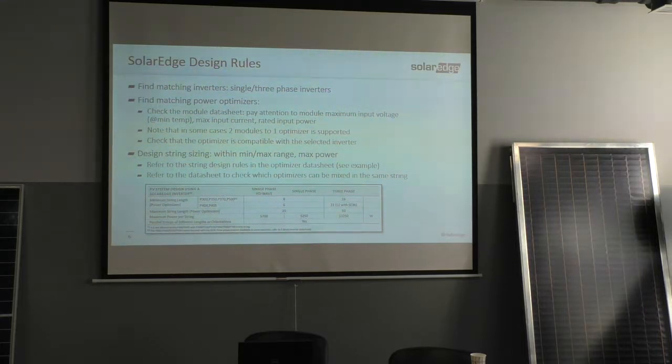So both points have to be reached. Less than 50 volts, because of the safety feature, and less than 11,250 watt. So if you have 300 watt modules, then obviously it will not be 245, but less.